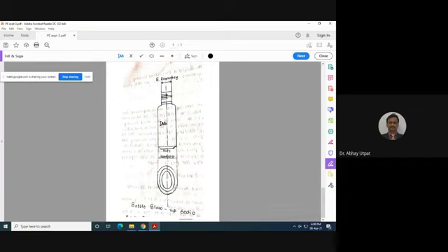So this is called blow ratio, and it varies from 1.5 to 3. This blow ratio is the maximum part finished outer diameter divided by the diameter of the parison. Same thing I told. Now this blow ratio also depends upon the parison temperature and parison thickness.